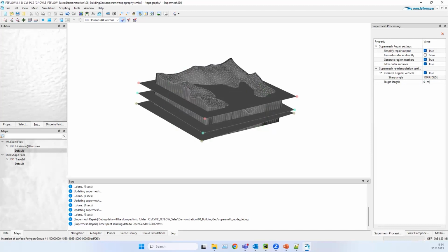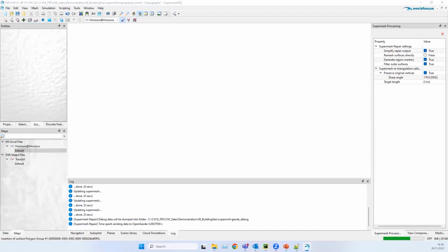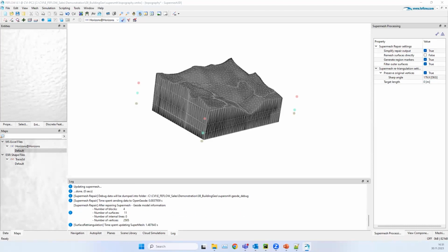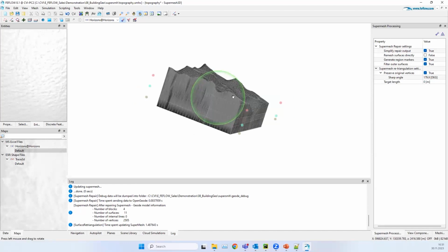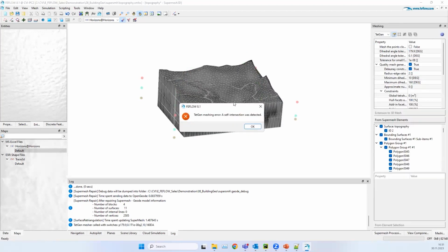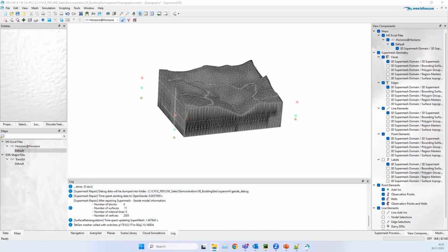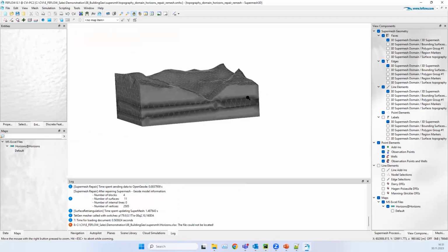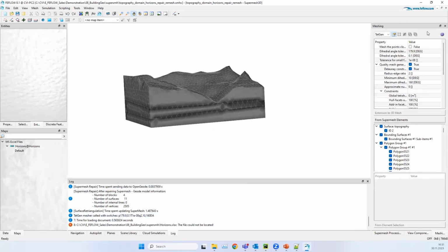So I can use the time in parallel to see the questions. Okay, or probably I leave the questions at the end because it's finished. So we can build the surfaces. If you run the mesh generator, there is a problem because I need to clean the surfaces. Sorry, I need to remesh the surfaces first, which will look like this. So the surfaces now are a bit cleaner, and this is meshable.